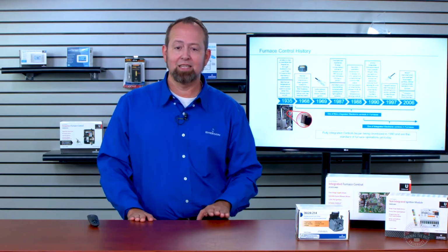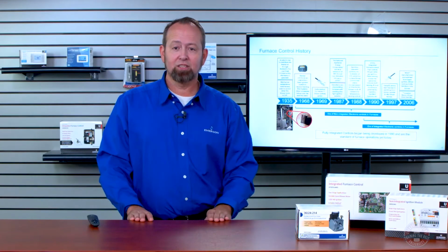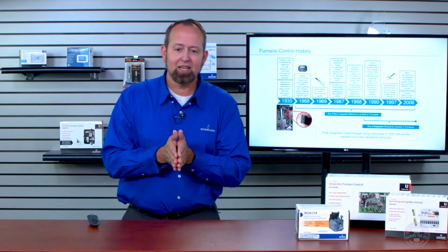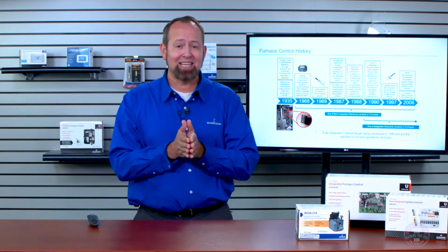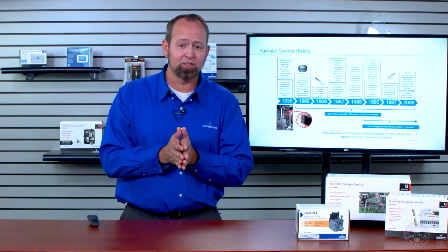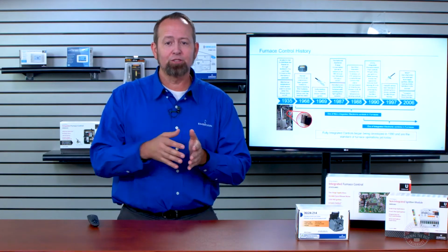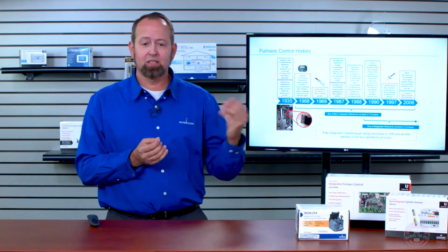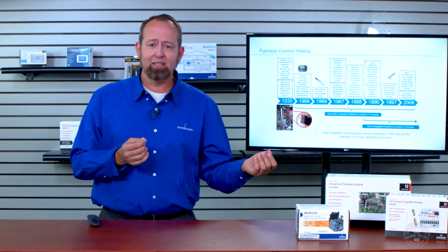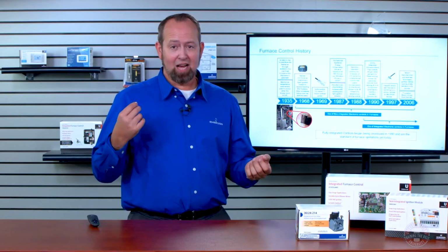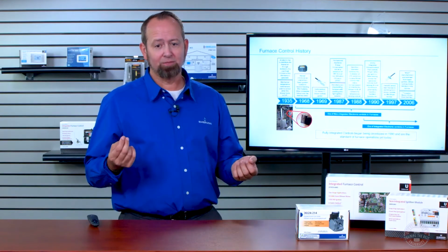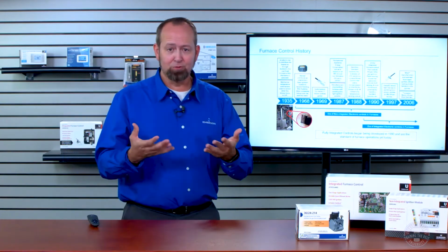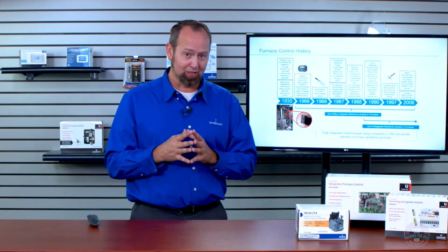Two years later, in 1990, we had the introduction of the fan timer and the ignition system coming together. And so 1990 is what I call the beginning of IFCs, or integrated furnace controls. And that is currently what we're using even yet today. A couple more slides here. We went from this silicon carbide in 1969 to silicon nitride, which is what the hot rod igniters are, in 1997. And in 97, Trane and Lennox led this movement of silicon nitride, and they led it with 80-volt igniters.